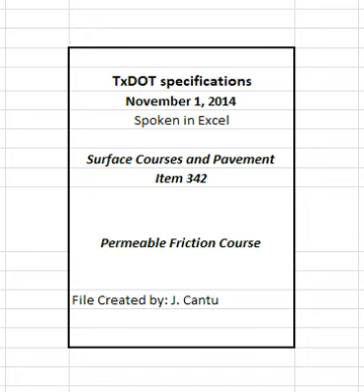2.3.1 Performance graded, PG, binder. Provide an asphalt binder with a high temperature grade of PG 76 and low temperature grade as shown on the plans in accordance with section 300.2.10, Performance Graded Binders, when PG binder is specified.